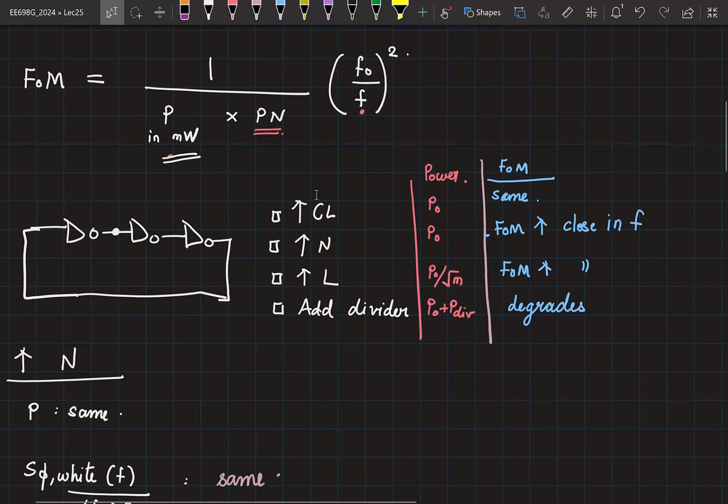Current is reducing, which means to charge the same capacitance, you will take a longer time. Right. So now again, this comparison. This is what we have gotten from the theory while making a lot of assumptions. So you can expect to see some changes as you run the simulations, but this is your underlying theory. Then you will run the simulation and then you can choose what is better.